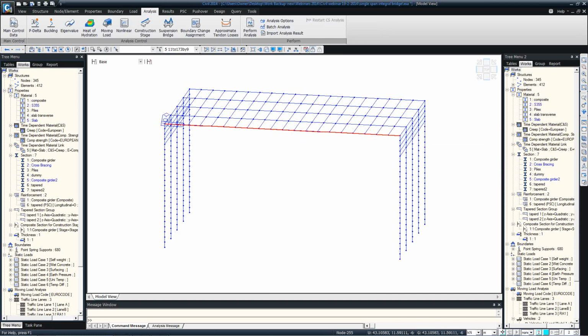There is another question: the vehicle load for the case of special vehicles where we have straddling. The lane width is, say, 3.6 meters and the wheel spacing is 2 meters. Actually, for straddling vehicles, if you specify 2 lanes between which the vehicle will straddle, internally the software creates multiple lanes between those 2 lanes and places the vehicle on different lanes with the 2 meter spacing, and then gives you the worst effect.